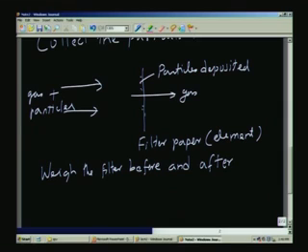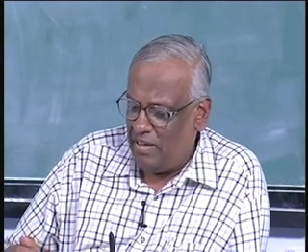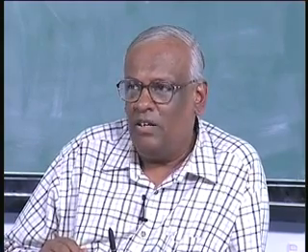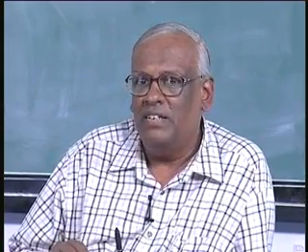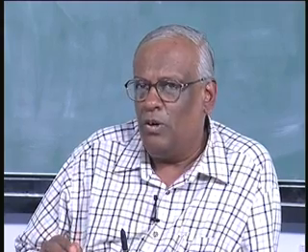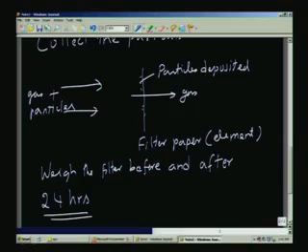For example, in typical cases it may be about 24 hours. So, you collect the material for about 24 hours, having weighed the filter element at the start, and after enough material is collected, we can weigh it, and we can then find out how much of the gas has passed through the system. So, in 24 hours, what is the total volume flow?